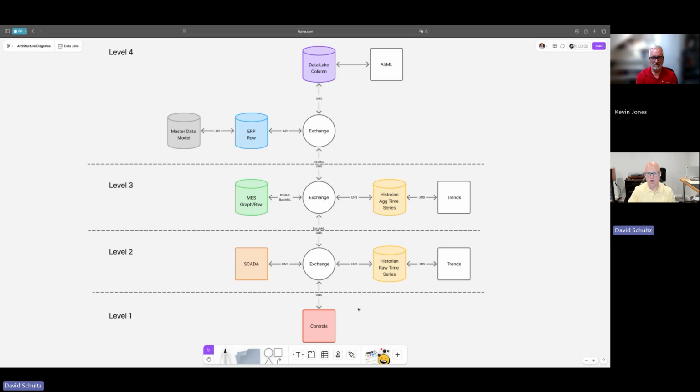Going back to this concept of a unified namespace, what we've done is we've added intelligence as we've integrated this information, starting with just basic asset models that are controls. We've now added some higher level, more detailed information at the SCADA level. We've also introduced things that are coming from our manufacturing execution system and or our ERP. So we've added that context of not only our time domain information, that SCADA data, telemetry information. We also know what product code am I running, what's this work order or production order from the ERP, who's doing this type of work, along with all the other information that's there.